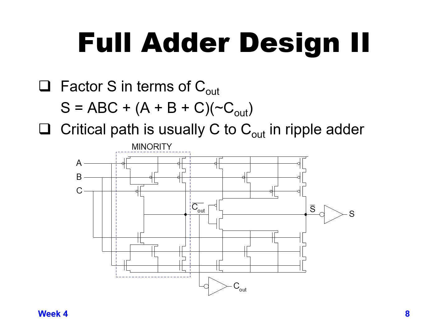In terms of doing it this way, one of the benefits it gives us is that the critical path of the logic function through the full adder is our carry path, because the carry goes from bit to bit to bit, whereas A and B are determined by each individual bit, which has its own A and B that are there before we start the carry. And so the carry, having to go to the higher order bits, has to go through all of the lower order bits first. So the carry is the critical path through the adder.